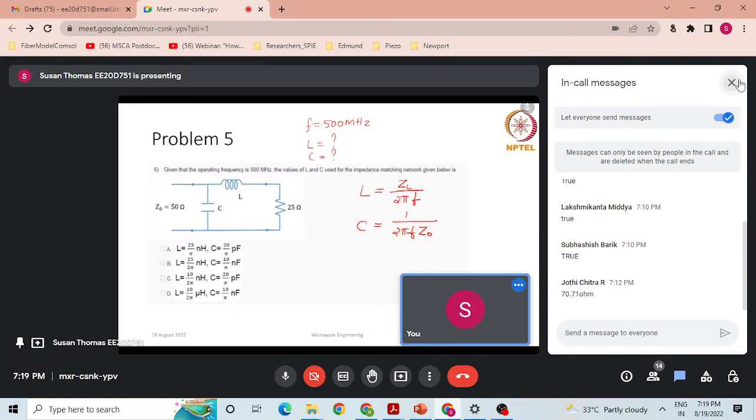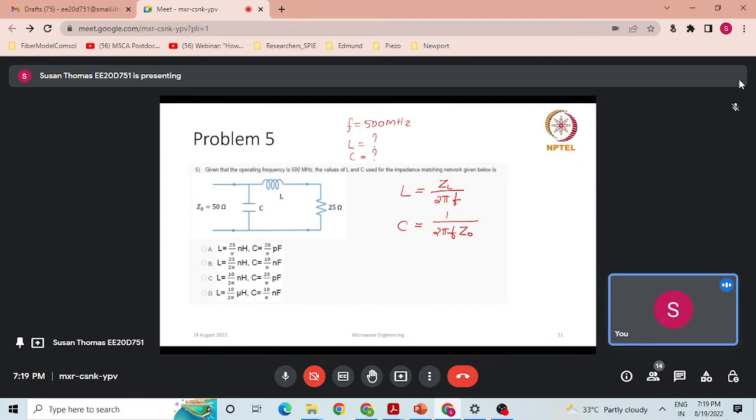You know the value of ZL and Z0, and you also know the frequency. So this network is something like this, which we have discussed before, jB and jX. If you notice, this is ZL and this is Z0. In the very beginning I had mentioned, whenever the real part of ZL, that means RL, is less than Z0, we use this kind of L section network.